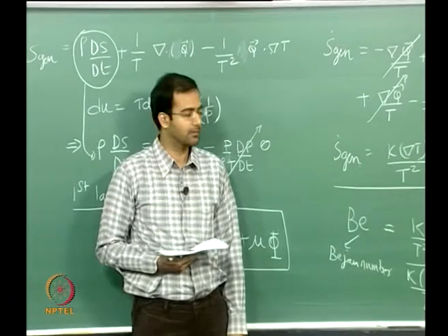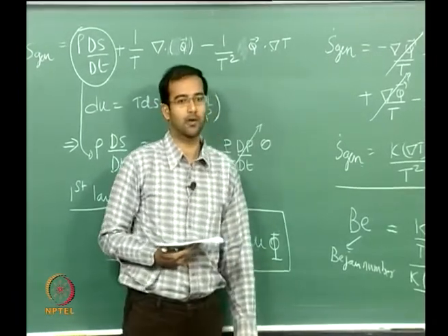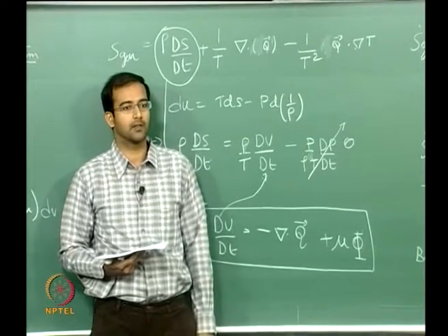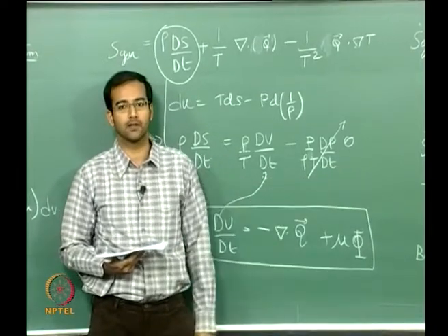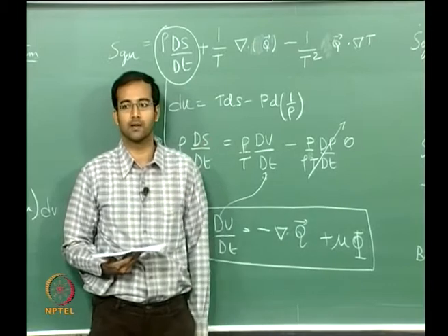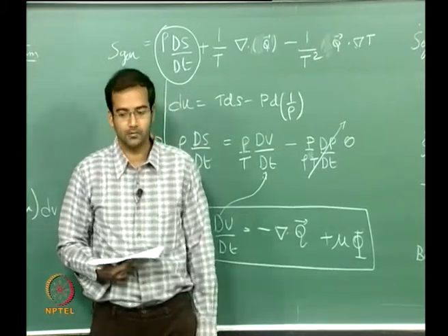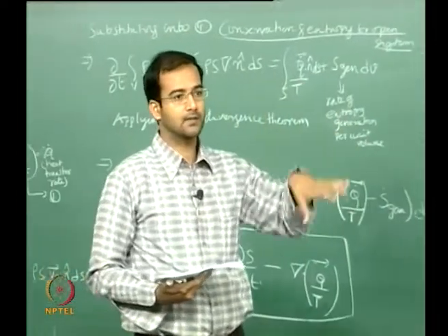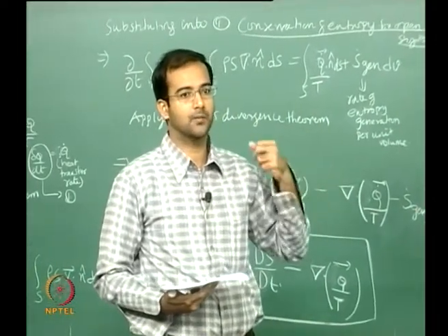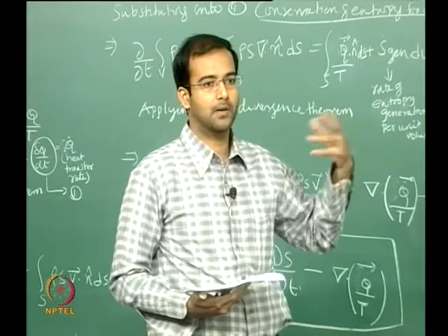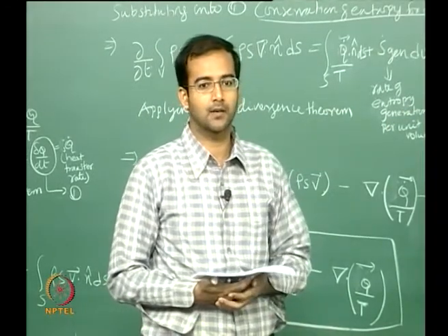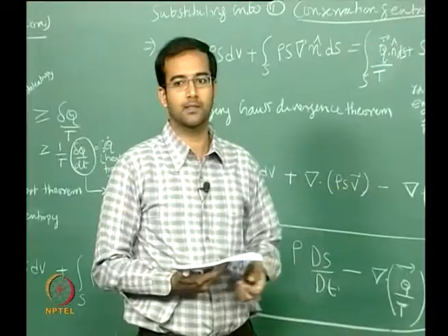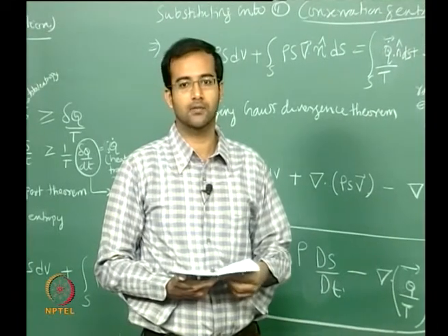Basically this can be plotted just like you plot your isotherms and heat flux lines. You can plot the entropy generation due to each of these, and visualize how it looks. It is a very useful tool. You can see in which location of a particular system your entropy generation is by the conduction part and where it is by viscous dissipation, and if you can try to reduce the viscous dissipation by some method, that will also reduce the entropy generation.